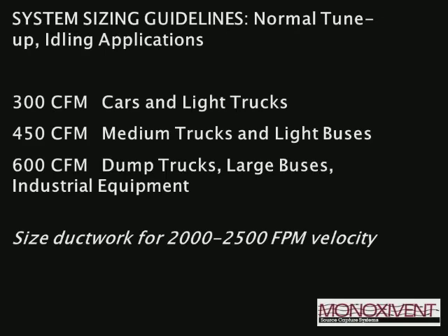And again, we want to size the ductwork for approximately 2,000 to 2,500 feet per minute. The reason for that is that's what it's going to take to allow that particulate to stay in the airstream. Again, we don't want anything falling out of the airstream.